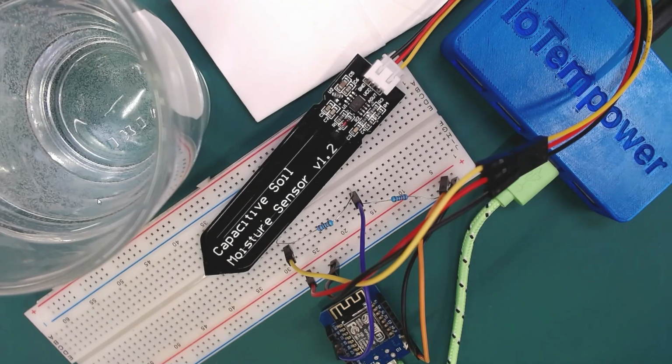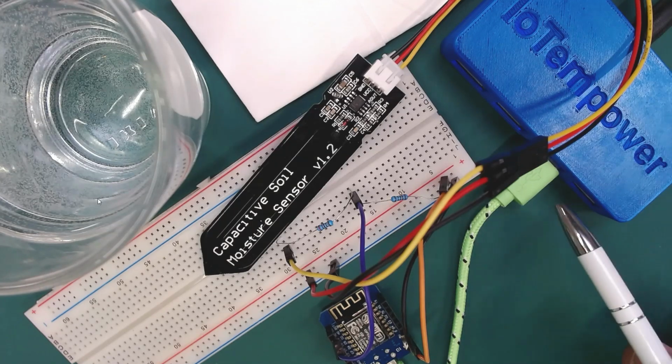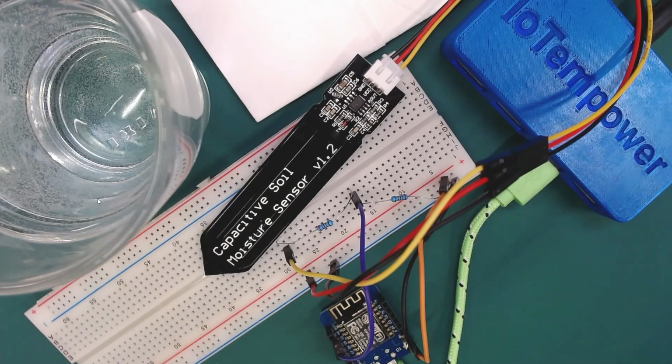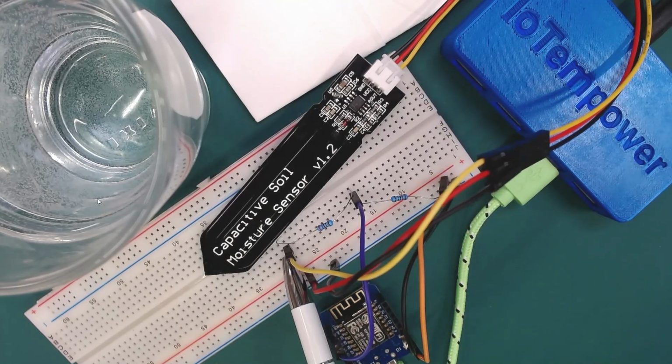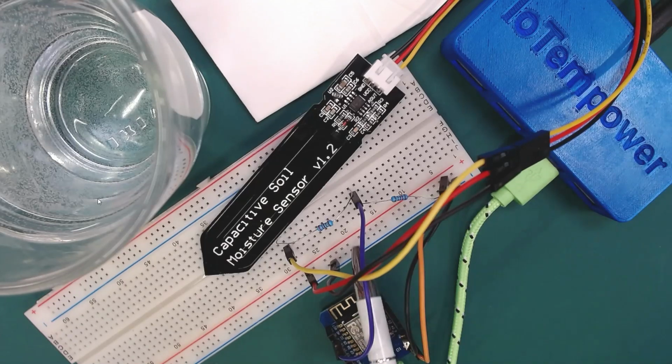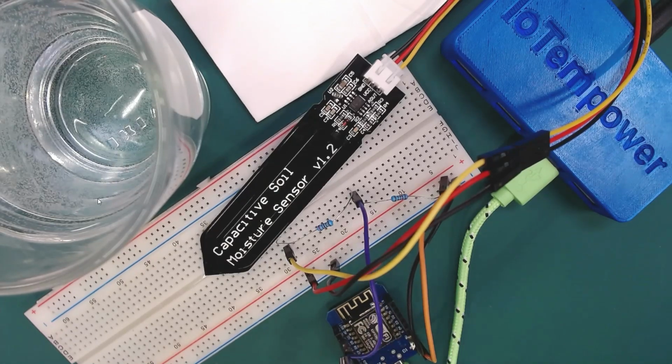So this is pre-flashed here. This is why we power it directly from the wall power, and then through this voltage divider we get to the analog port here, which is connected to the higher resistor, and then it falls down to ground through resistors, and this is the value we are actually measuring here. Later we'll put this into water, and then we will see some changes to the values.